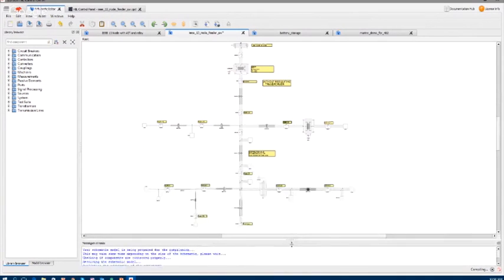And then let's see what we are compiling. So we are compiling this IEEE defined 30-node feeder. We are going to run this model now in offline regime to see how this works and to see how accurate our models are. So this is one of the models that is defined by the IEEE community to serve as a testing model to test and verify the accuracy of your simulation platform. So our models are in less than 1% error, which is quite precise. IEEE is allowing 5%.